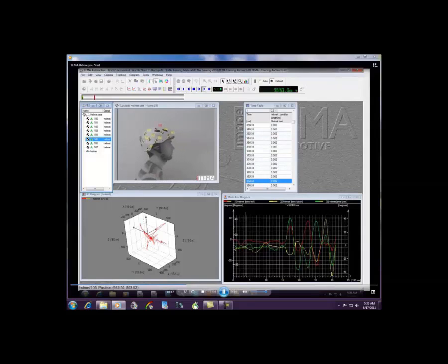This is a 6 degree of freedom test in which the rigid body is the helmet. The targets on the helmet need to have been surveyed. One of these points, in this case the point 100, is the XYZ 0 point in the first frame. All motion in subsequent frames is based from this point. The roll, pitch and yaw angles are derived from those used in the helmet survey. The Static program will allow you to take images from all around the rigid body and develop this survey using only one dimension, the distance between 2 points on that body.